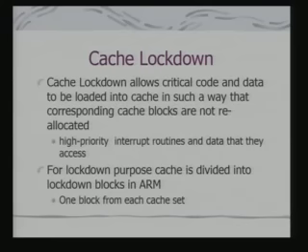Okay. So, your data from main memory can be loaded onto these blocks. So, that will not be really replaced. Now, if you remember, we had talked about even in the DSP processors, we had talked about loop cache. That means frequently accessed loops being loaded onto the cache, so that there is a minimum overhead for loop execution. That also has a similar idea, that there is a dedicated memory where you store a particular loop which is very frequently used, and you may force it not to be replaced at all.